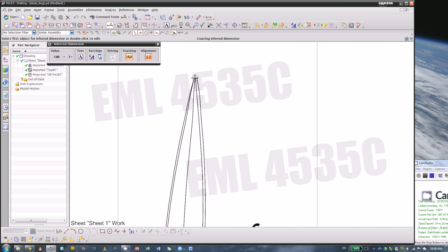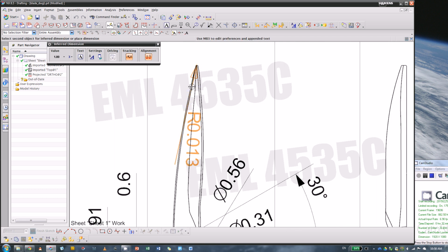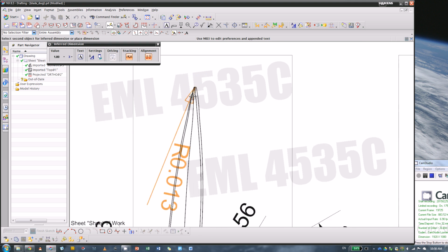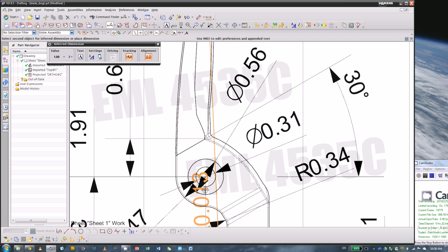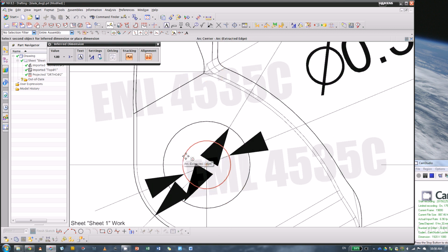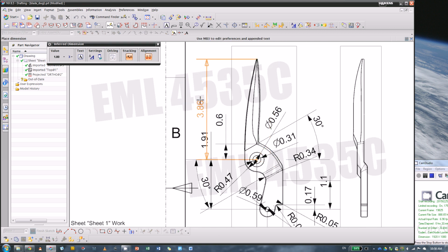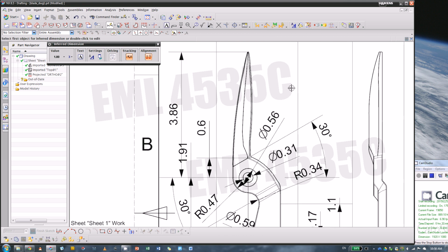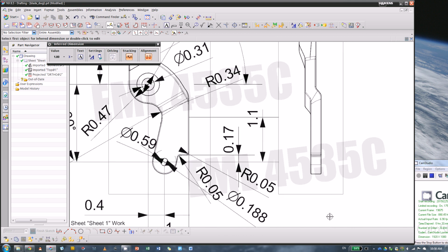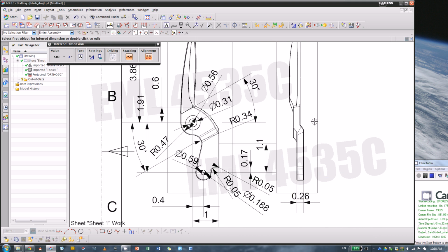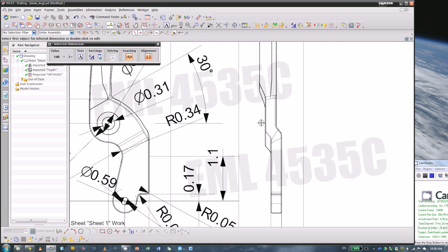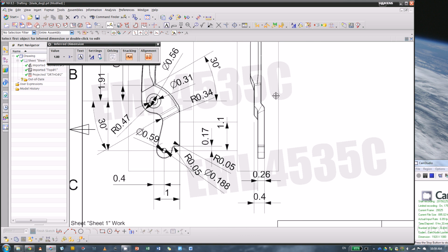Then it depends on what you click. If you click that, that's a little fillet there. So then if you click a second item, center of the arc, it'll show the distance between them. Then probably come here, you can add some thickness of the parts, and okay, how much from the top to the bottom, depends on which side you're pulling out.